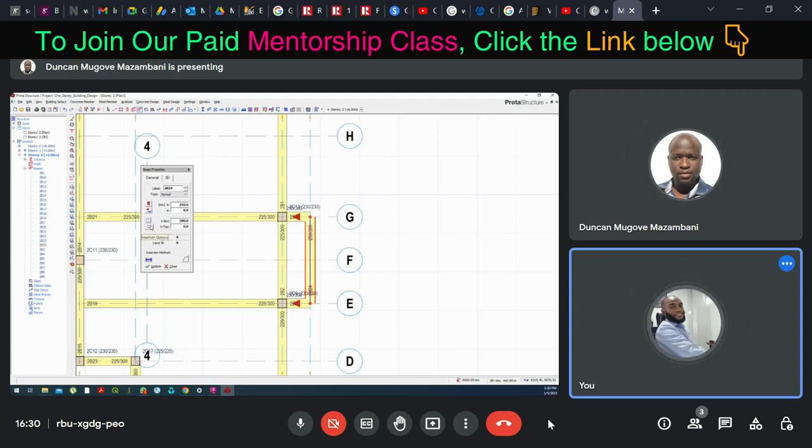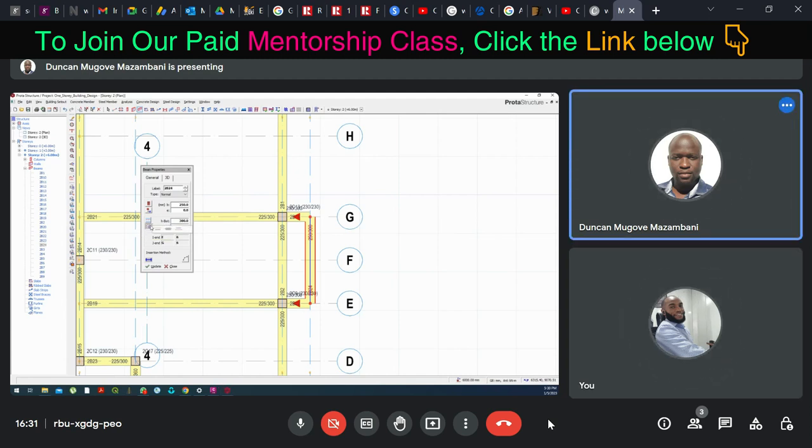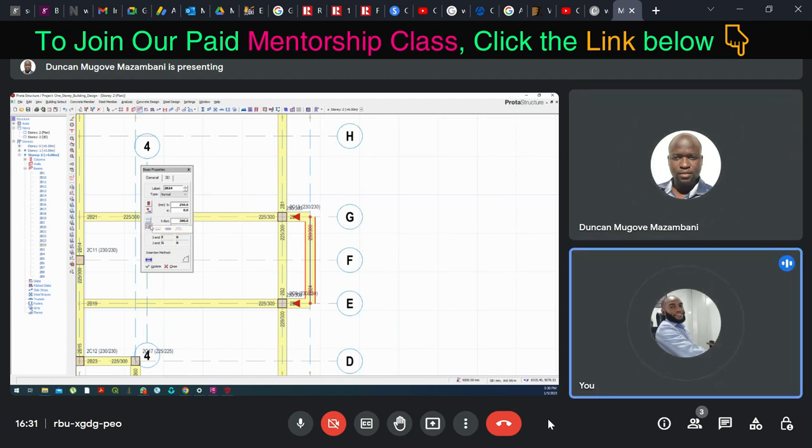Yes, this one. Click there, the insert option. Now you can see that we have three options. We want to make this beam flush with the grid line, so choose the last option, that one, and then click on update. If you choose that, it will make the beam flush with the grid line.